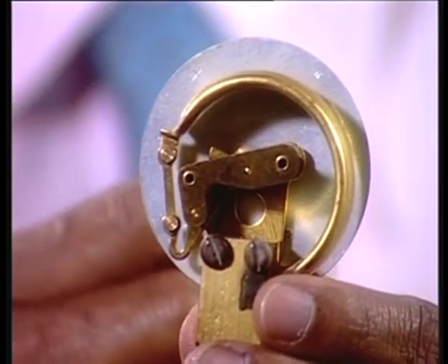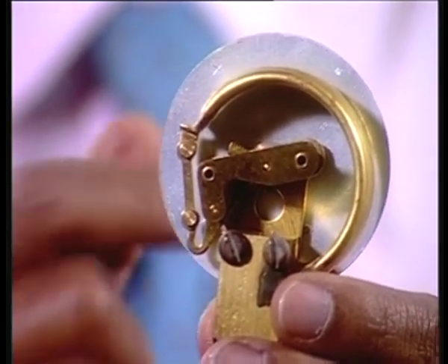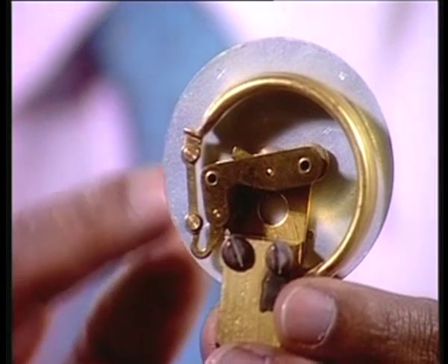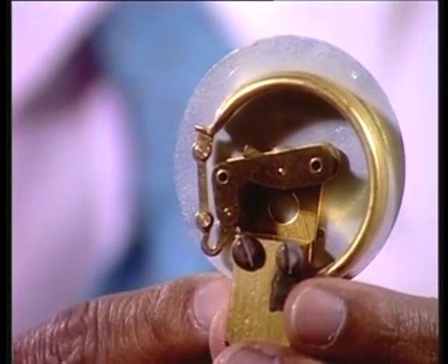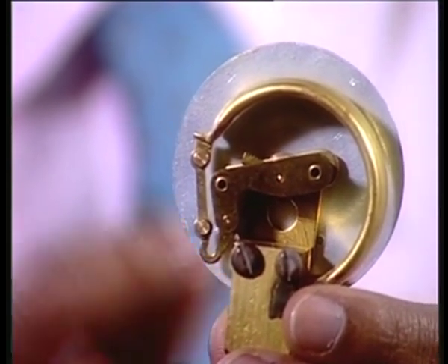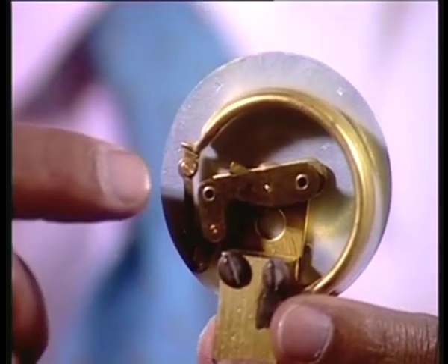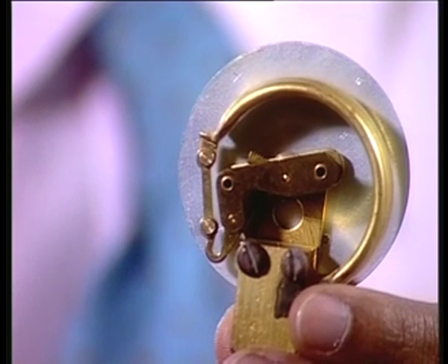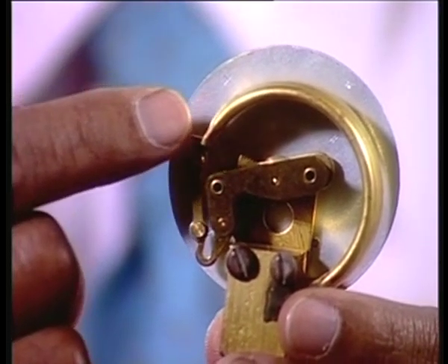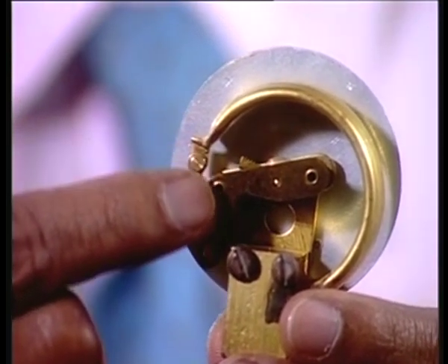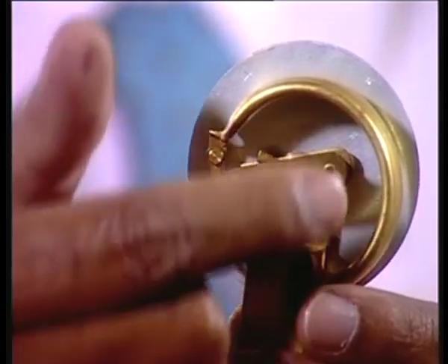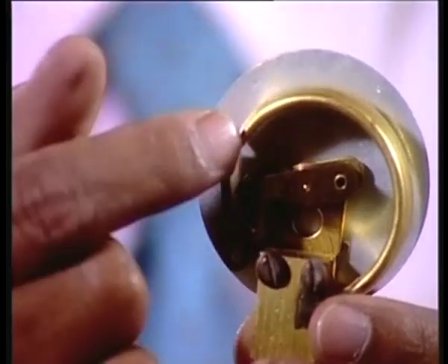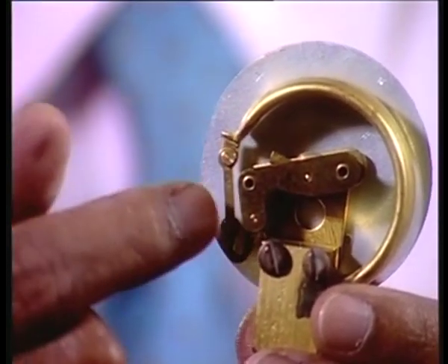Now the advantage of that type of thing is that I am getting more deflection, because usually this is for quite high pressure, right? But if I have a longer length of the C tube, because if I make only a single C, I won't get much deflection. So instead of that single C, if I make a spiral that does not end here, it comes down, we have several turns, then it ends. And that closed end is again connected to the lever.